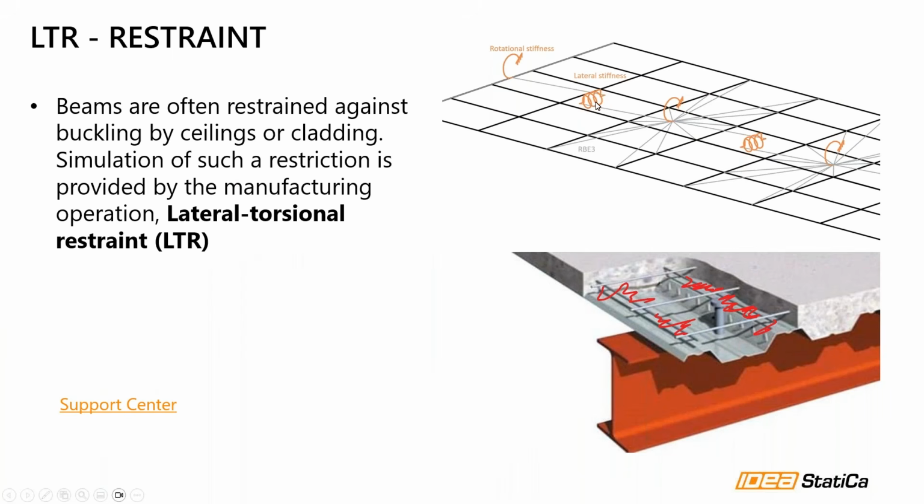There are some lateral stiffness springs that can be assigned inside IDEA StatiCa, restraining the lateral movement, and also the rotational stiffnesses that are linked with constraint equations to every node, transforming the stiffness using weights to the other points on the top of the flange. So it's important to understand that we are just supporting the continuous and the discrete redistribution of those constraints.